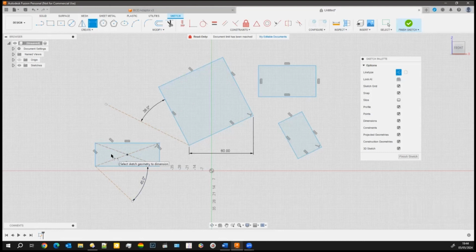So the 2.1, to recap, is point A to point B, horizontal or vertical. The center one is a rectangle equally bound around the center point, again horizontally or vertically. If you need a rectangle at an angle, then it's going to be a 3.1 where you can then put the angle in. I think that more or less covers the rectangle. I'm not aware that we've missed anything. I don't think so. Let me just check.